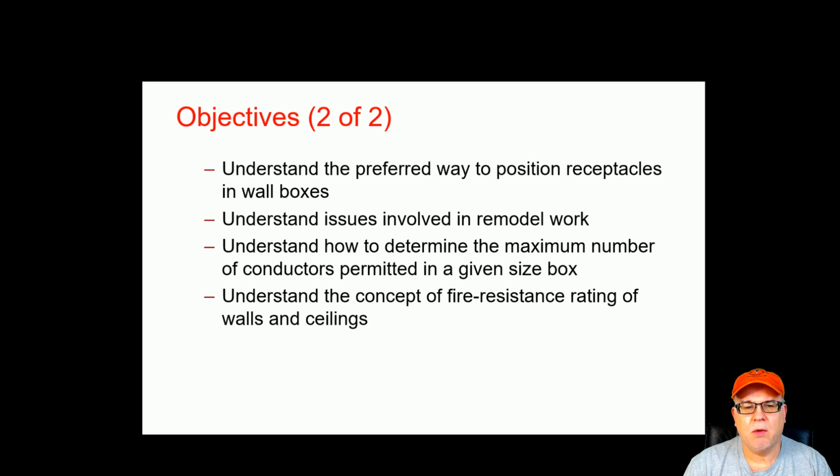We'll also understand how to determine the maximum number of conductors that are permitted in a given box. This is what we refer to as box fill, and that's going to be in Article 314. So we're going to dabble in that a little bit in this unit. And then we're going to understand the concepts of fire-resistant ratings of walls and ceilings, whether it's a 2-hour rating, 1-hour rating, and those types of things.